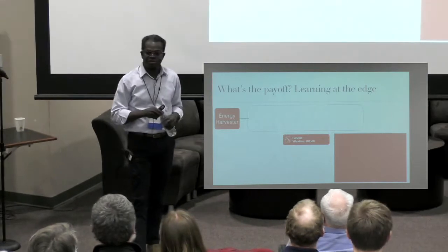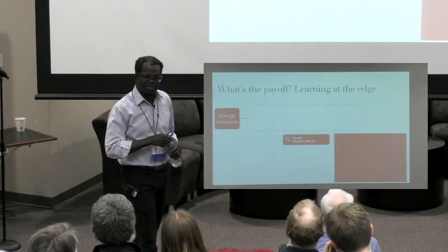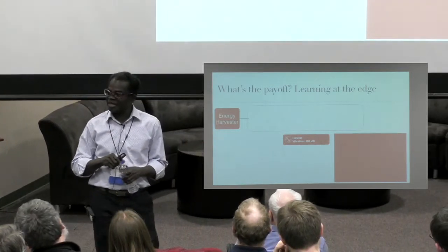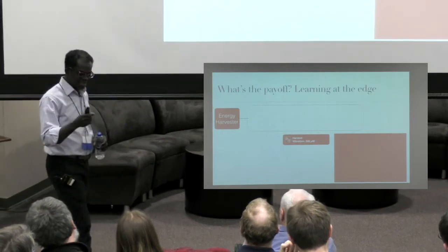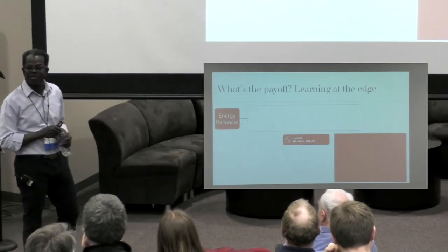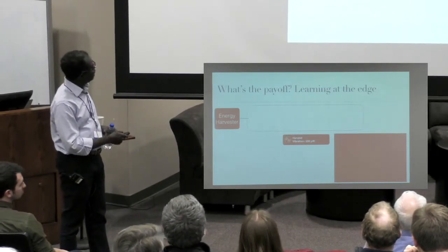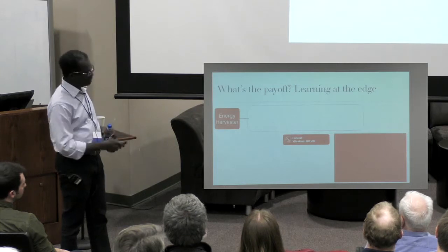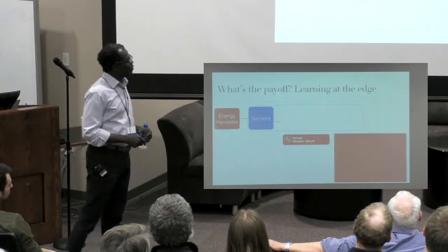It could be measuring the response to every car that passes by. It could be detecting that, predicting how it's going to respond. If a crack starts developing, it will respond differently. And that little smart device that gets energy from just the vibration of the beam itself will then fire a radio signal. Okay, so these kinds of systems that are deployed way at the edge would harvest energy from the environment, temperature, vibration, light. Will have sensors.